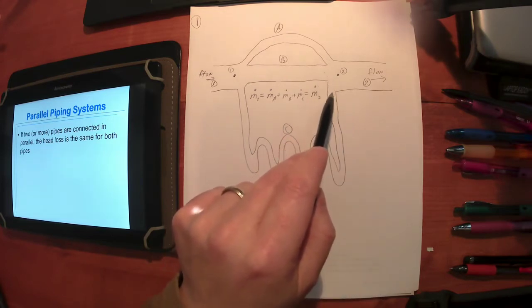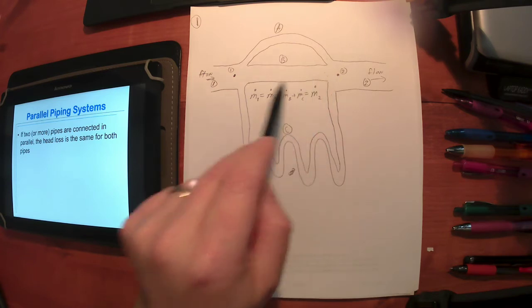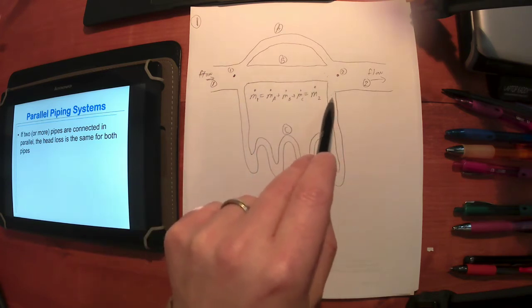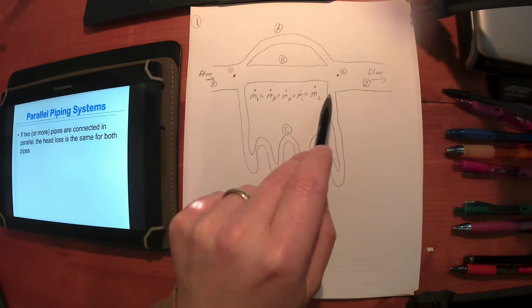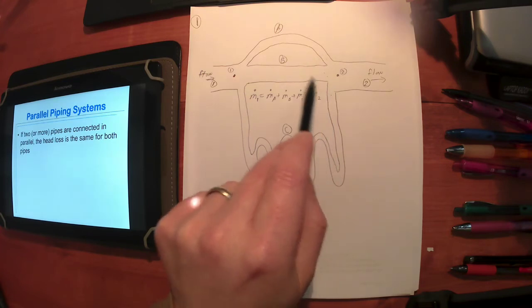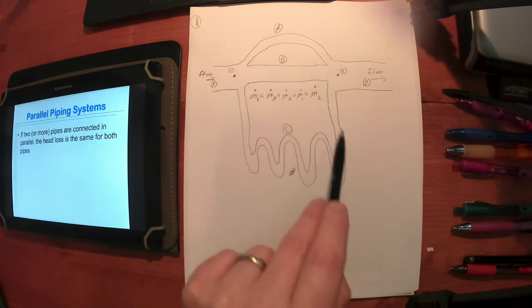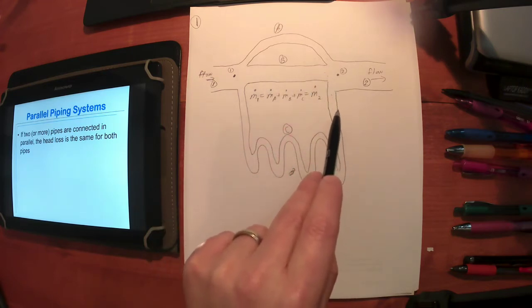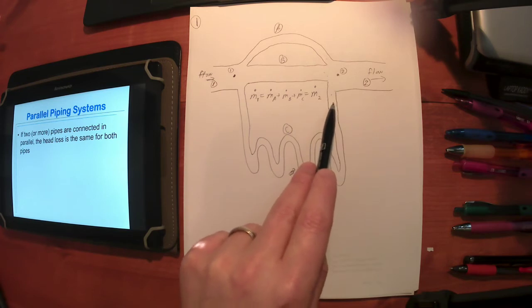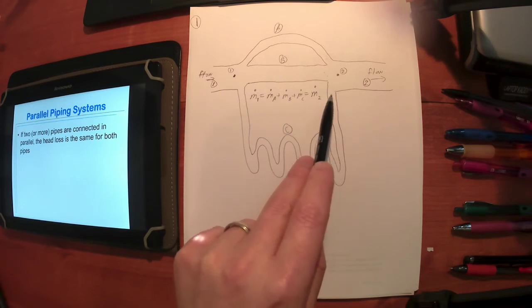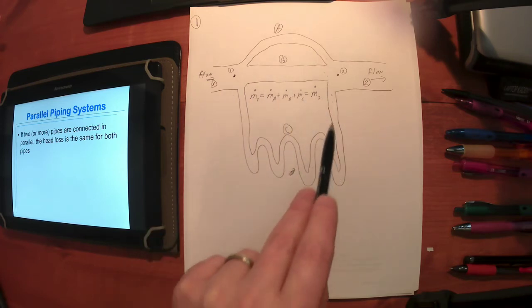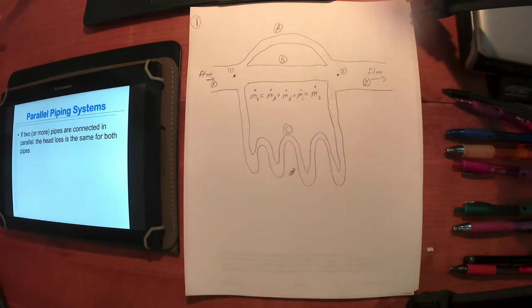Again, if the pressure here is lower than the pressure there because we've got all this craziness, so it's got to be more pressure loss, right? Think about what happens if the pressure here is lower because there's more pressure loss: then some of this fluid's going to come down here and flow in here. So some of the fluid's going to come out of B and flow into C, and it'll do that for a brief instant until enough fluid from C pushes it back out and everything starts going again.